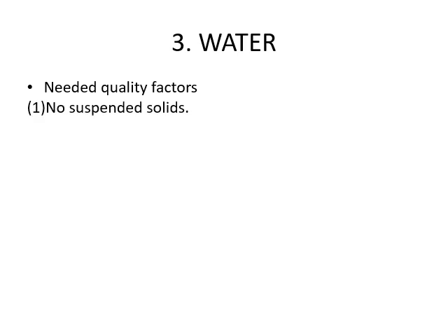Any suspended solids are likely to be filtered out onto the fiber, yarn or fabric. High or low pH could cause spontaneous uncontrolled reactions to occur. Metallic ions may give rise to discoloration, stains or chemical damage, that is catalytic tendering of the substrate during bleaching.